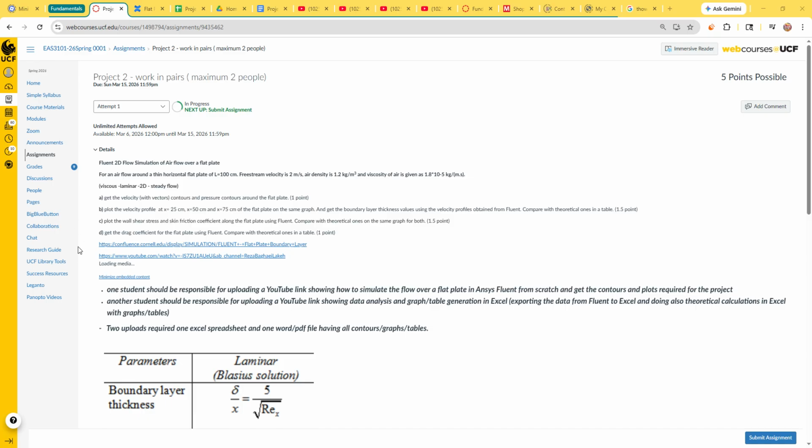Let me go back to pressure. You can see the vector well. Here's the velocity vector. Even though it's on top of the pressure contour, the velocity is smaller, lower near the boundary layer. Pressure has this big spike right here, and it gets gradually lower as it gets to the pressure outlet.